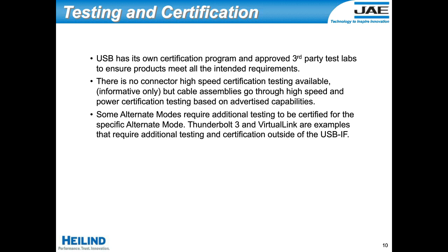There's basically no connector high-speed certification testing available. There are recommended high-speed performance benchmarks. However, those are all informative specifications. So when you submit these connectors to certification testing, the high-speed signal integrity testing is actually not conducted. Cable assemblies, on the other hand, do all have to go through signal integrity testing, as well as power certification.